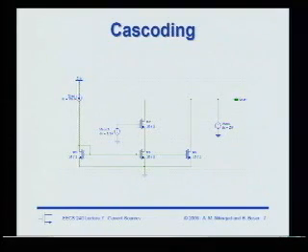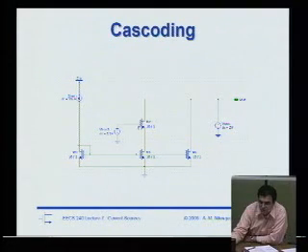This is basically a simple cascode, and the way I'm going to solve this headroom problem, partially, is by realizing that there's no reason why I have to bias this point at 2 VGS plus 2 VT. I could always lower this voltage to the point where I just come to the threshold of keeping this device in saturation, right at the boundary.